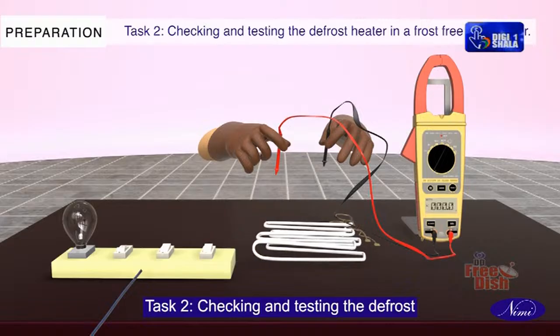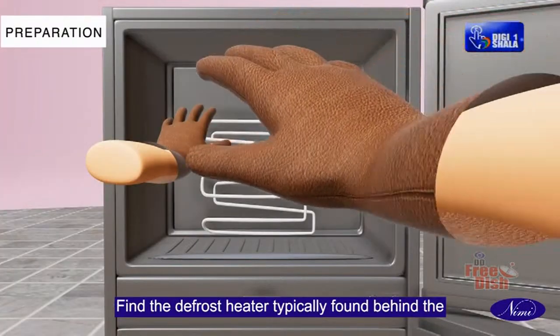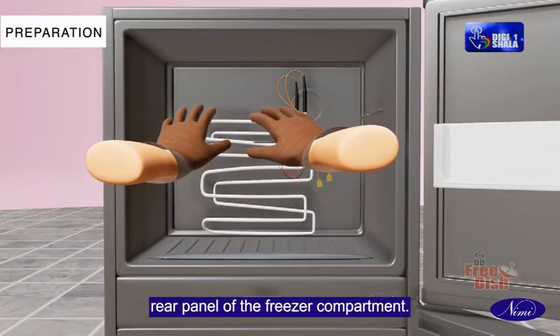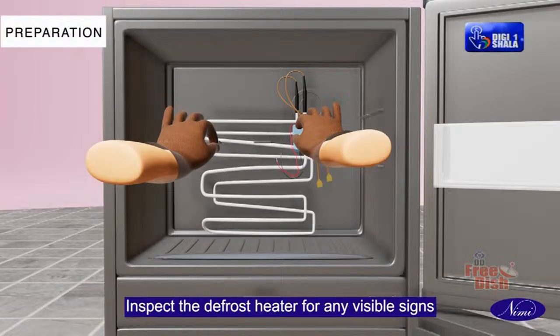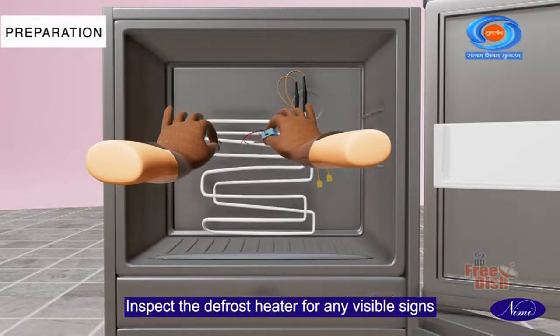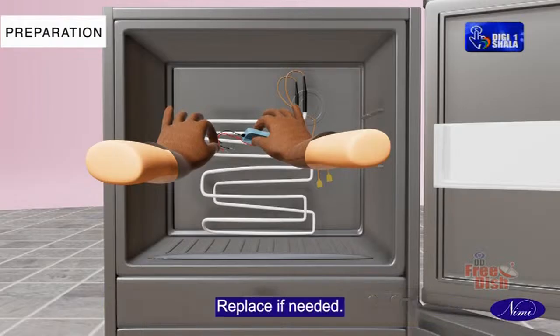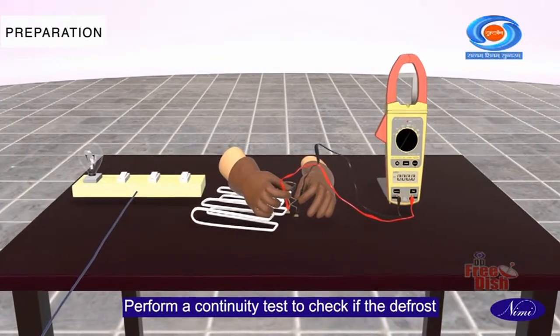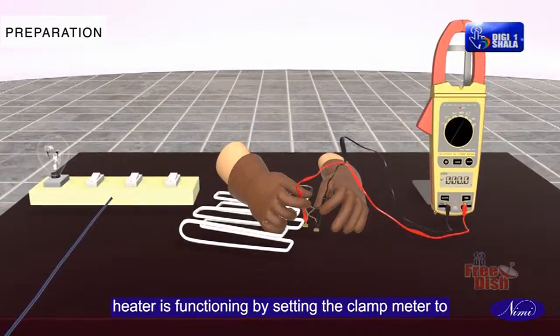Task 2. Checking and testing the defrost heater in a frost-free refrigerator. Find the defrost heater typically found behind the rear panel of the freezer compartment. It may appear as a coiled wire or a glass tube. Inspect the defrost heater for any visible signs of damage such as burns, breaks, or discoloration. Replace if needed.